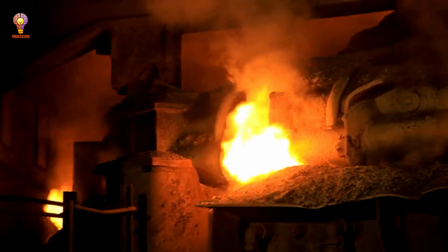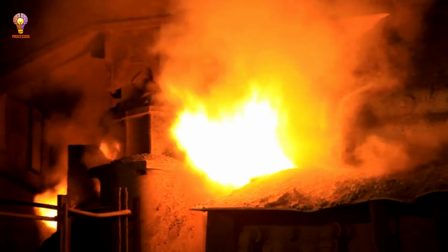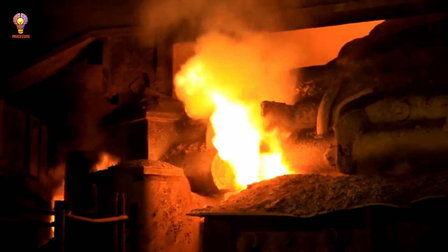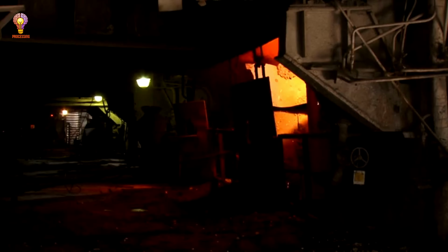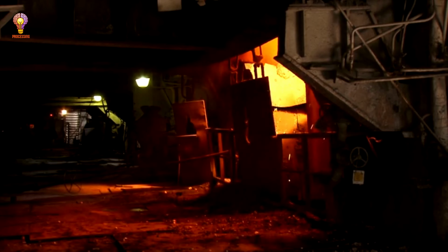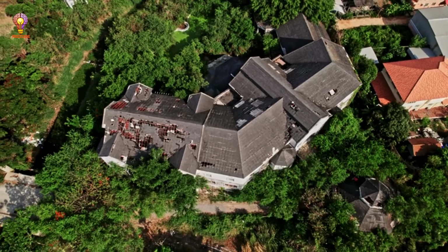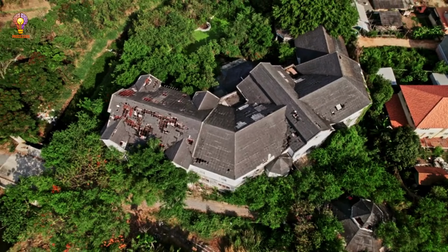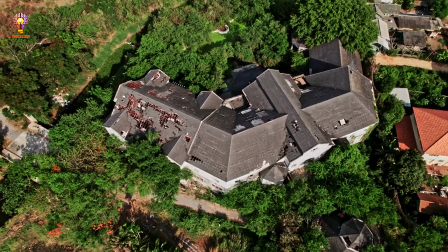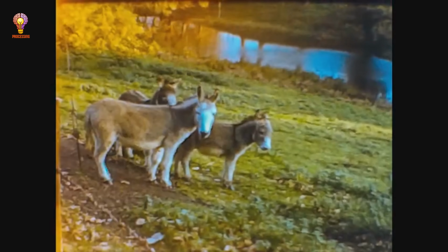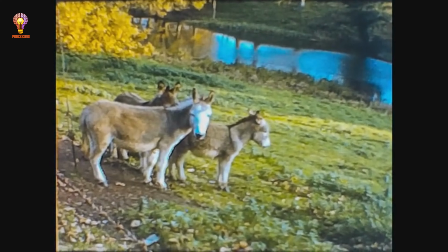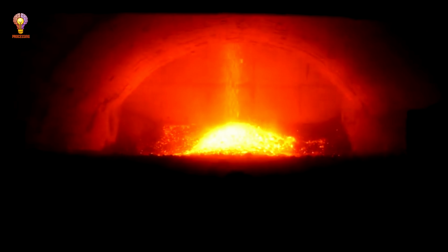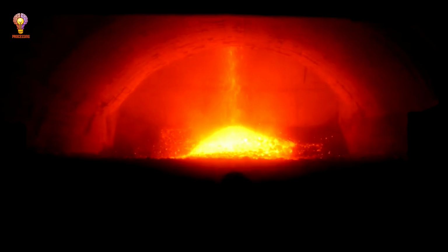considerations. 1. Iron making, blast furnace versus direct reduction. Blast furnace. The blast furnace process is the most common method of producing molten iron. Iron ore, mainly Fe2O3 or Fe3O4, is combined with coke and limestone. Coke acts as both a fuel and a reducing agent, and limestone helps remove impurities. The blast furnace uses high-temperature air blasts to melt the iron ore, producing molten pig iron and slag, a byproduct